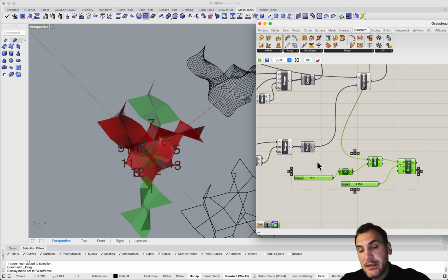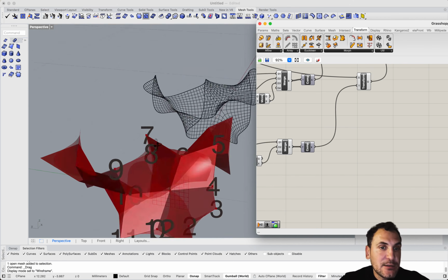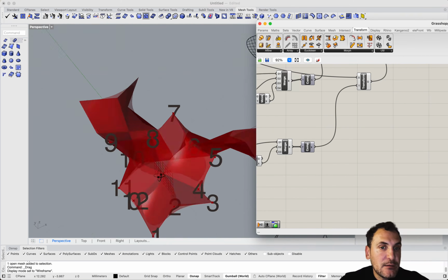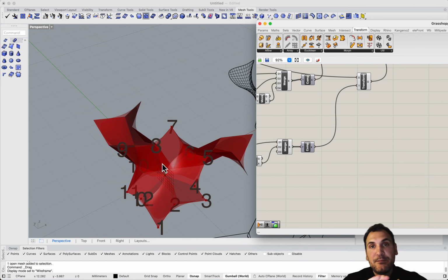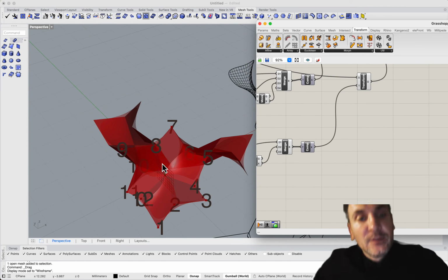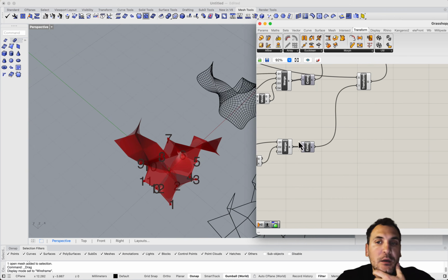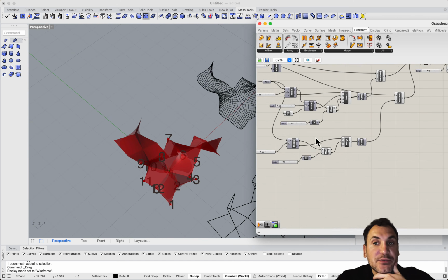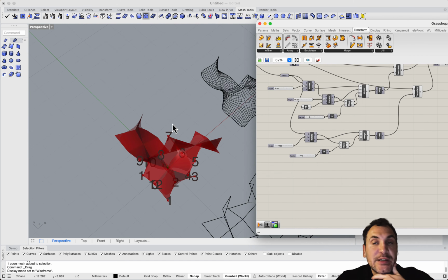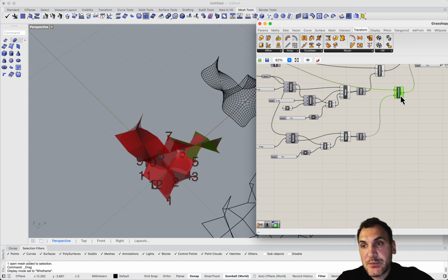So that's not what we can do. That's kind of the issue. You want to rotate it using the center geometry, and if you don't, it won't rotate it correctly. It will rotate it around this origin. So we need to actually do another transformation on the base geometry and then translate it here, which is going to be a bit tricky, but I guess we can do it.